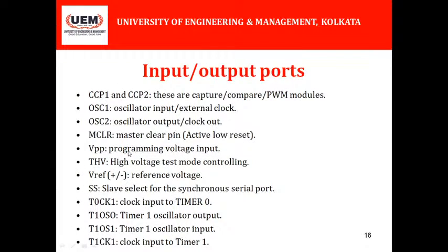CCP1 and CCP2 are two modules performing capture, compare and PWM, or pulse width modulation, operation. OSC1 stands for oscillator input, OSC2 stands for oscillator output. MCLR stands for master clear pin, VPP stands for programming voltage input, THV stands for test mode controlling high voltage pin, VREF stands for reference voltage which can be positive or negative, SS stands for slave select for the synchronous serial port.